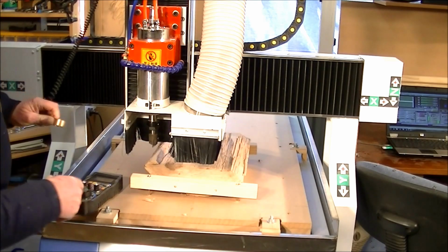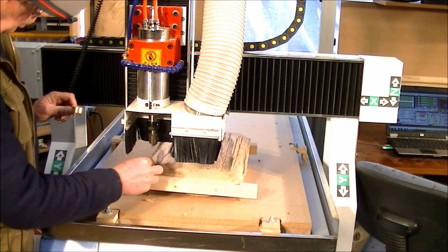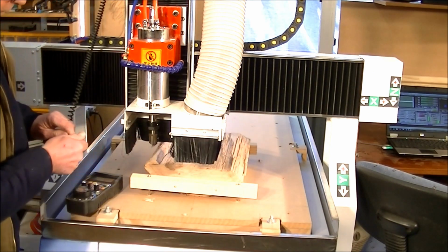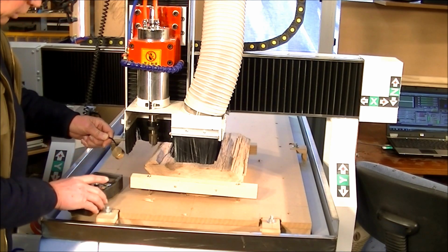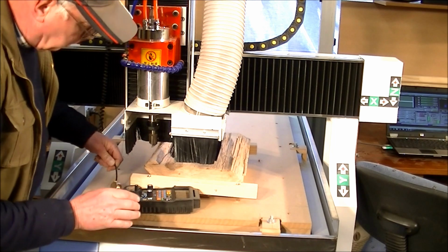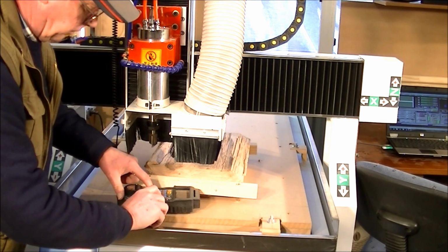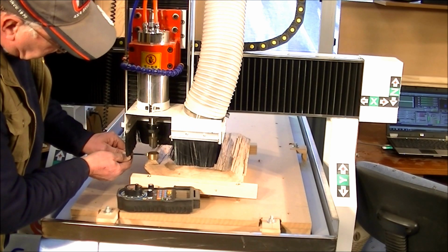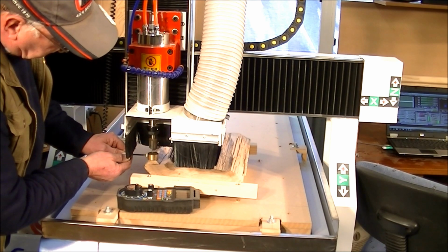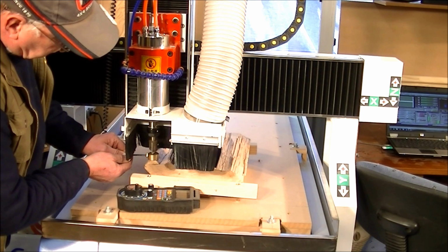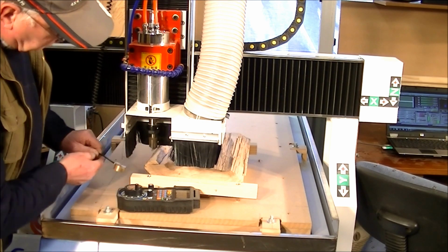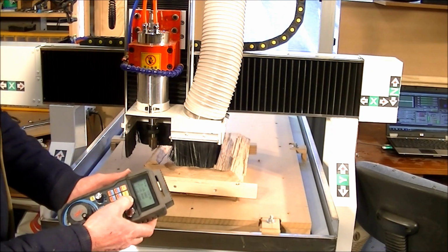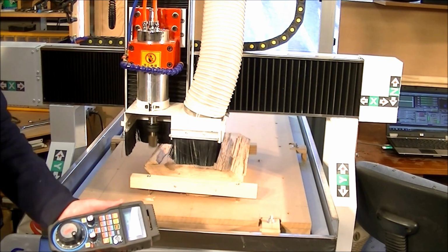Okay, so we've now gone over the whole surface, and I've actually repositioned the 0 point further over this way because it's just going too far over there. So now we set the new Z height, which is simply done like that. Having set the new Z height now in the program, we just now restart the program.